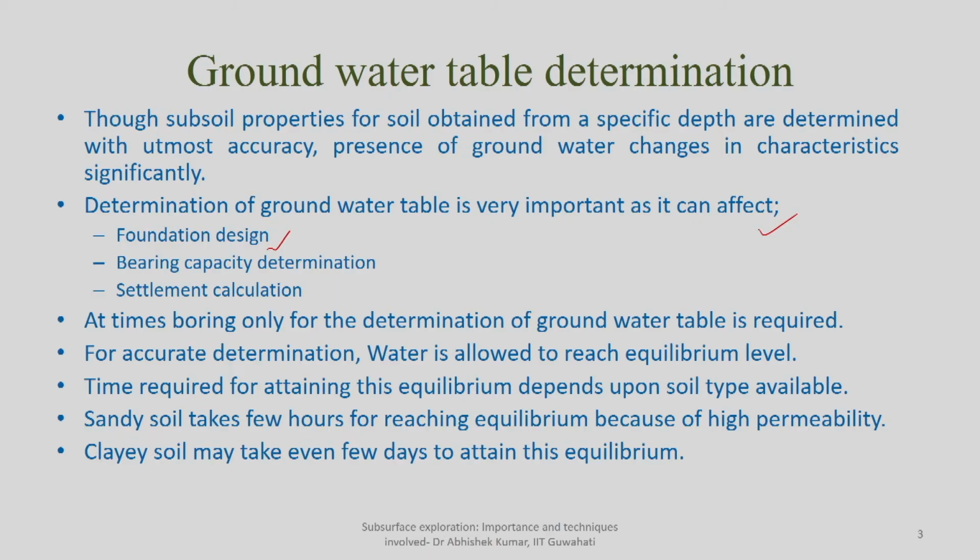The second one is bearing capacity determination. As I mentioned, soil in a stiff or dry condition will behave completely differently from the same soil which is partially or fully saturated. So, depending upon how its behavior is, its bearing capacity will change. Because its bearing capacity is changing, overall the stability of the foundation will change.